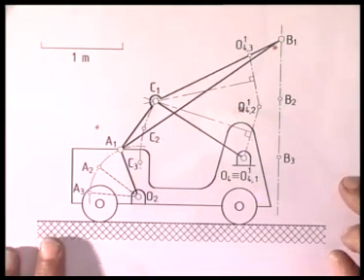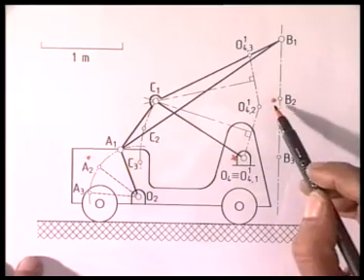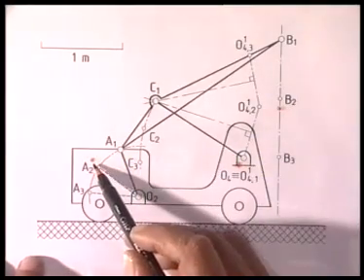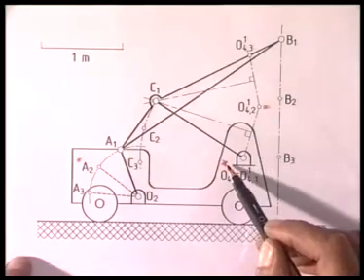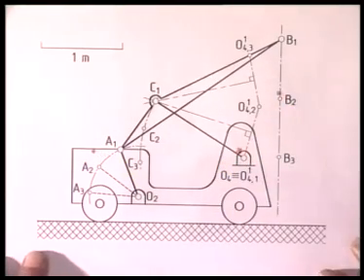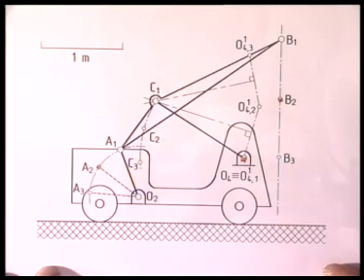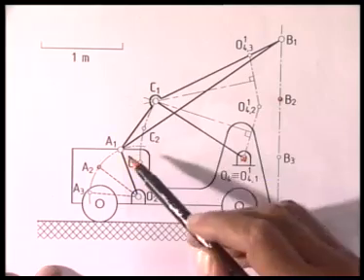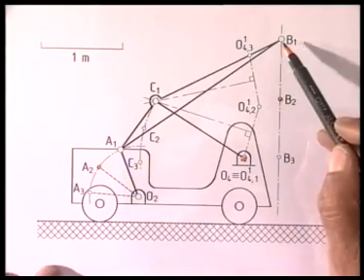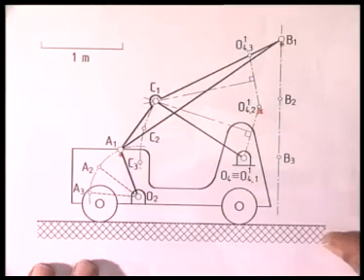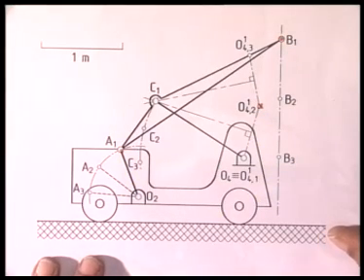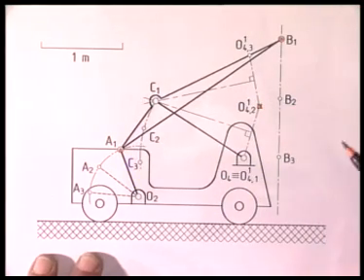So I move, if you remember, this point represents B2, this point represents A2, and this cross represents O4. And they define the relative position of A, B and O4 at the second configuration. Kinematic inversion means this relative position should not change, though I am not allowing AB to move from A1, B1. So I move this tracing paper, A2 coinciding with A1, B2 coinciding with B1, and wherever O4 goes, that point I mark